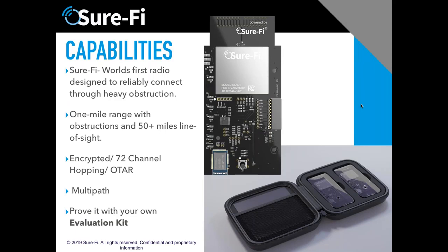So a telephone entry system will be possible with that voice. A CCTV situation has too much data for us to go across the SureFi radio. It would be wonderful, and I wish I could say that's the truth, but we really are a low to medium bandwidth type of product. So we can do controls like relays, we can do Wiegand, RS-485, RS-232, and we are getting a solution ready so that we can also do voice, but at this point that's kind of the end of the type of bandwidth that we can provide. So hopefully that helps Avi's question.